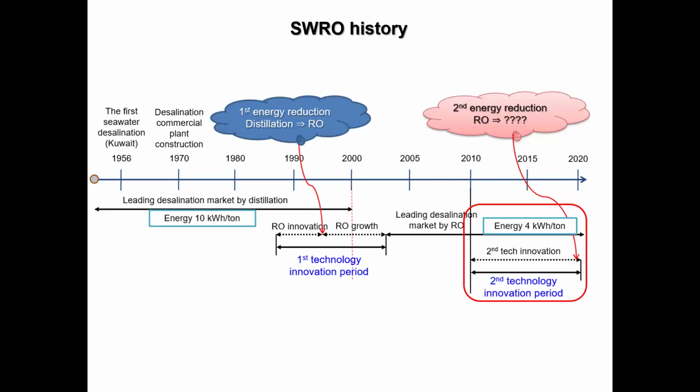Because of the pressure exchanger. The second innovation: first is more about the membrane, the reverse osmosis membrane development. And then the second one is the pressure exchanger. So we developed how to recover pressure, like you recover heat. You have waste heat, then combined with the heat exchanger, you absorb the heat, and you can save a lot of energy. Same as the pressure.